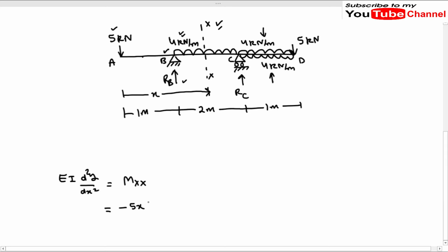Okay, so how will I add these two terms in this equation? First of all, I will draw a vertical line, because there will be discontinuity in the loading at B. Due to this reaction RB, and due to this UDL which is applied on the upside of the beam in the segment BC, the other term will be due to this reaction RB, and it will be positive because the reaction RB is acting upward, so it will create sagging moment. So it will be RB into x minus 1.